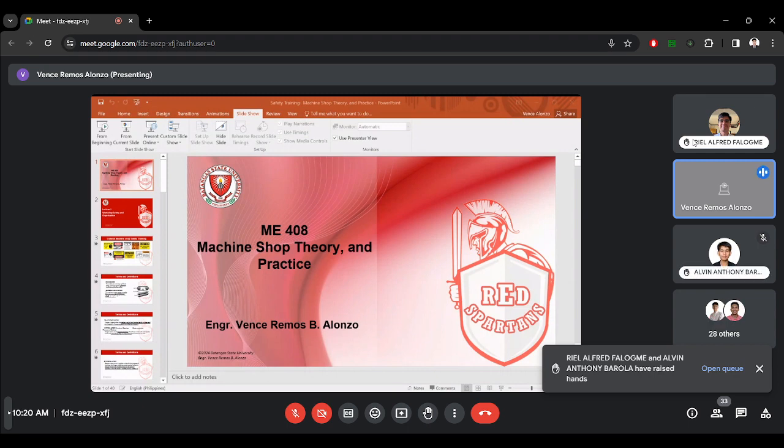So, transverse motion by definition creates a hazard when the worker is pulled into the pinch point or shear point, or is dragged by the moving parts into other moving parts. A cutting action, so rotating, reciprocating, or traverse motion. So danger exists at the point of operation where finger, head, and arm injuries occur and where flying chips or scrap material can strike the eyes or face.